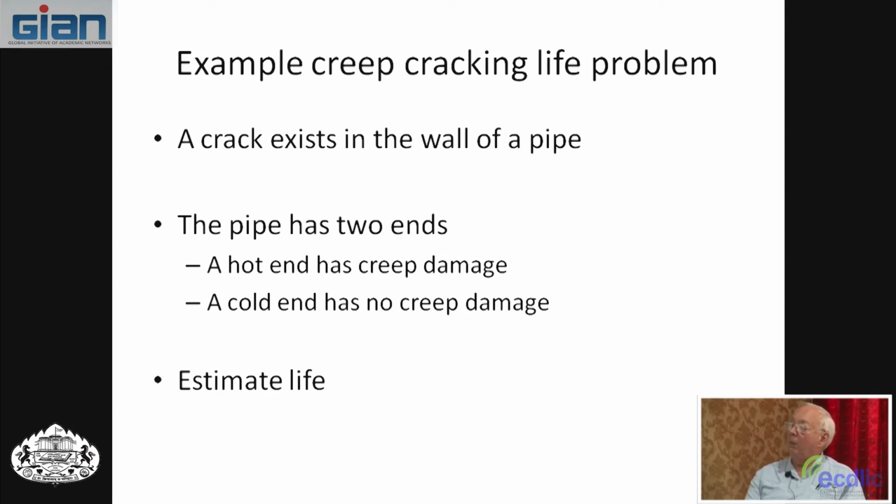Back when we first started doing creep cracking, people were saying that creep exists only in stress rupture, only in tensile loading and no cracking at all. And then one day a big pipe burst at a place in California where they had some kind of big steam pipe, and the pipe burst by having a crack that went for feet or meters, several meters long.